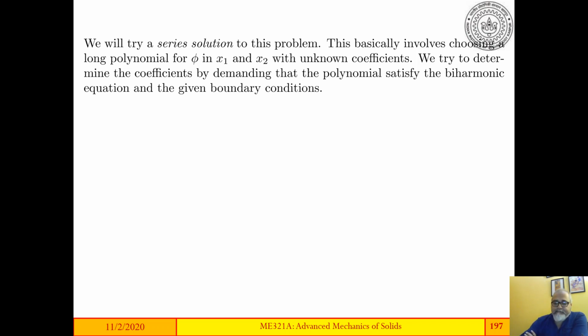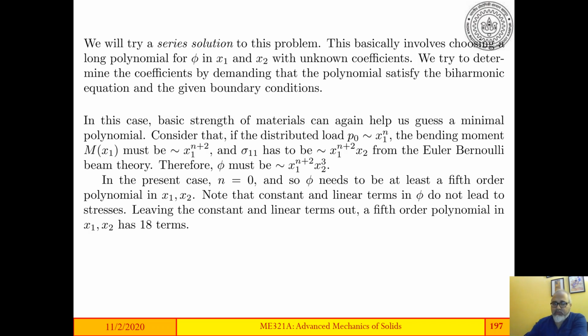Now, think of the situation where you are trying to guess the series based on the Euler-Bernoulli beam theory. So this is how you will go about it. You will say that, well, Euler-Bernoulli beam theory says that P naught can be a function of x1 to the power n. So P naught is the distributed load. It can be a function of x1.